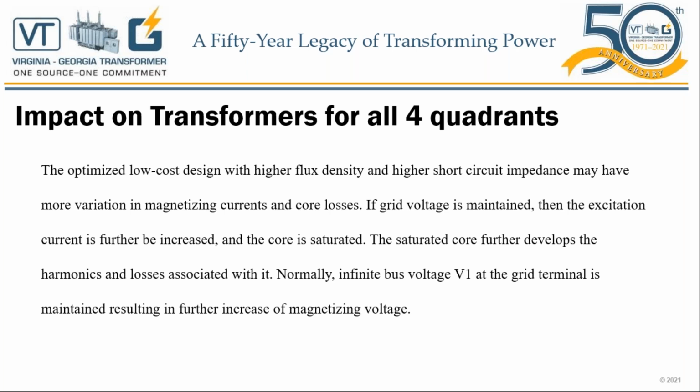But who uses transformers only for no load operation in the field? Transformers are there to supply the load, which takes it back to 105% plus load and plus the 0.8 power factor. Having said that, the optimized low-cost design with higher flux density and higher short-circuit impedance may have more variation in the magnetizing currents and the core losses.